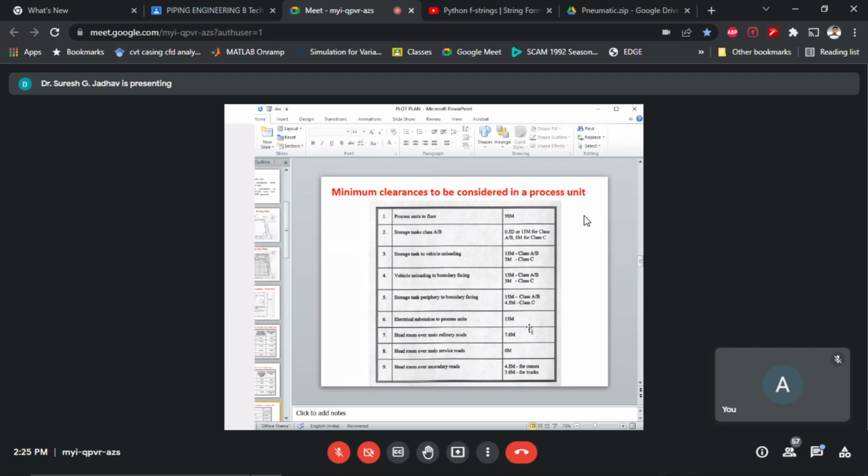If vessels in the installation are more than one, the longitudinal axes of the vessels should be parallel to each other. The top surfaces of the vessels are required to be made in one plane. Vessels installed with their dish ends facing each other shall have screen walls in between them.